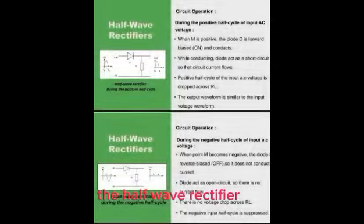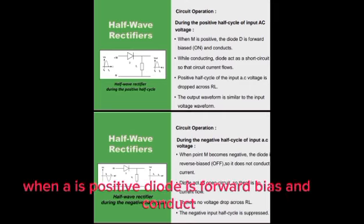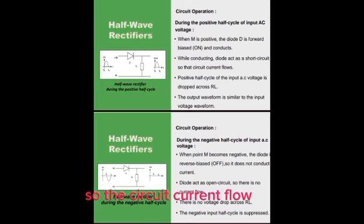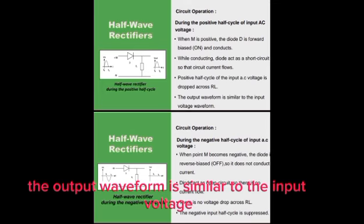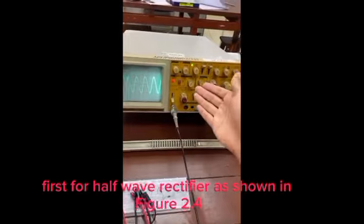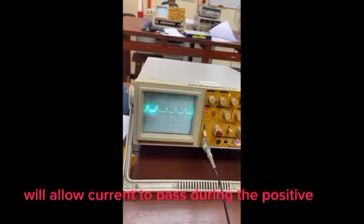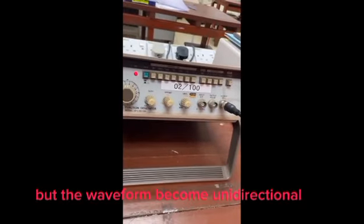The half-wave rectifier during the positive half cycle of the input AC voltage. When A is positive, the diode is forward biased and conducts. While conducting, the diode acts as a short circuit, so the circuit current flows. The positive half cycle of the input AC voltage is dropped across a resistive load. The output waveform is similar to the input voltage waveform. First, for the half-wave rectifier, as shown in figure 2.4, the diode 1N4001 will allow current to pass during the positive half cycle only, but the waveform becomes unidirectional.